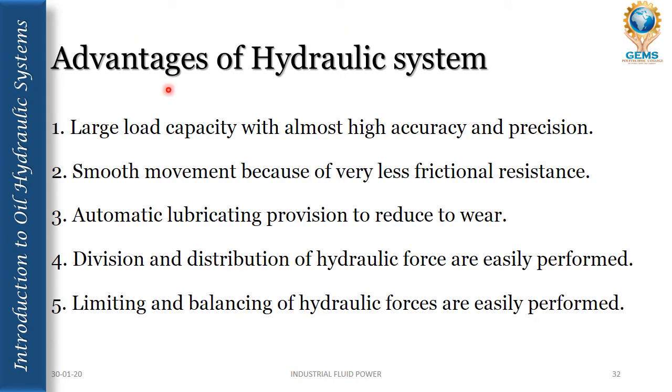Now let's see the advantages of hydraulic systems. Large load capacity with high accuracy and precision. Smooth movement because of very little frictional resistance. Automatic lubricating provision to reduce wear. Division and distribution of hydraulic force are easily performed. Limiting and balancing of hydraulic forces are easily performed.